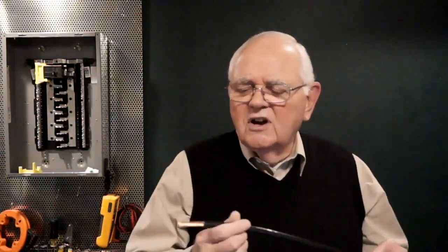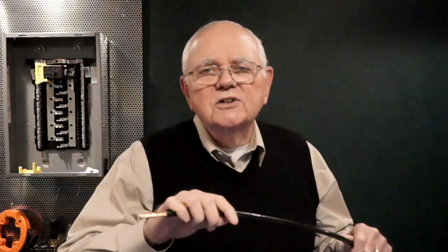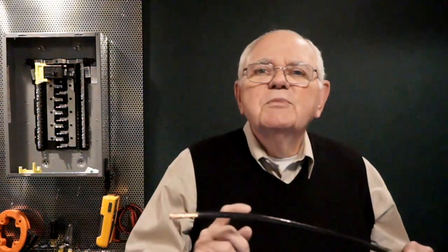On the other hand, our thermoplastic insulations have a lot of good properties to them, even though the XLPE type insulations are a little bit tougher and stronger. The thermoplastics, very commonly used, fairly easy to pull through conduits and so forth. It's interesting too, most of the insulation on a conductor is not there for insulation properties. Most of the thickness is being used for physical protection of the conductor. It doesn't take a lot of thickness of insulation to really give you, in this case, 600 volts of protection